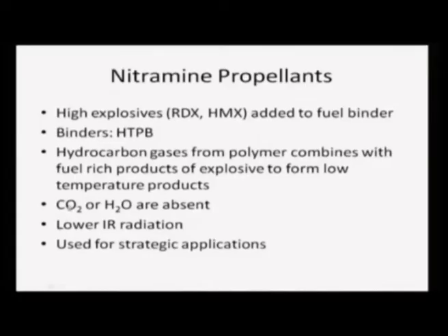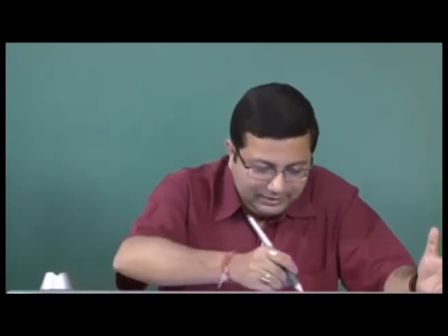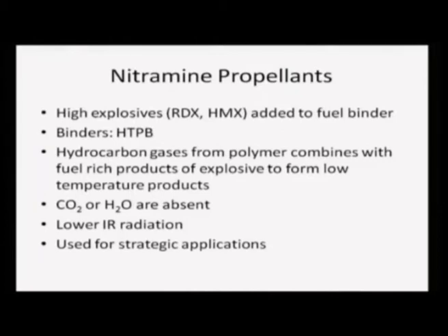So, carbon dioxide and water vapor are absent in this mixture. Typically, as you know, most of the hydrocarbons, when they burn, because they have oxygen, hydrogen and carbon, many times produce carbon dioxide and water vapor. But in this type of propellant, carbon dioxide and water vapor are absent. Now, what do carbon dioxide and water, particularly water vapor, do? It is a very good